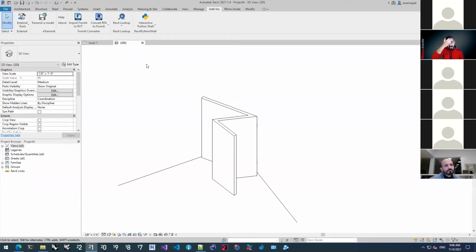I would suggest for best performance and best experience, if there's something that you have to make only once or twice, create it in the UI and place it in the Revit model. Maybe there's a family that you want to populate the model with. Create one or two instances of that family that is parametric enough and has the right properties, and use your script or Rhino.Inside.Revit to place it and set those property values inside your Revit models. That would be a decent approach.